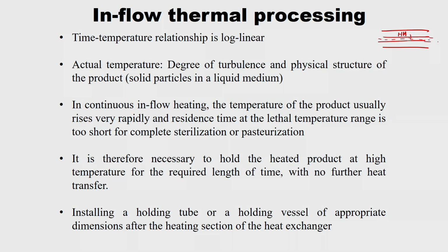So, the heat goes from the heating medium to the wall and then to the food, right. This time temperature relationship is also log linear. For example, m dot Cp dT upon T is nothing but U. So, this is nothing but the heat you have given, Q is equal to UA dT, right.